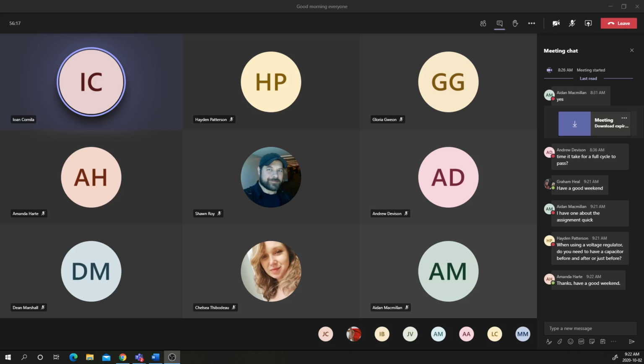Usually that capacitor is a few hundreds or few thousands of microfarads. The other two small capacitors that are connected at the input and the output of the voltage regulator are called decoupling capacitors and have a very small value. Actually, it will maintain a smooth output voltage. It will act as a buffer for the rectifier, actually for the regulator.